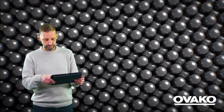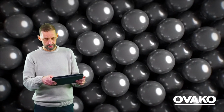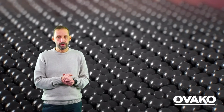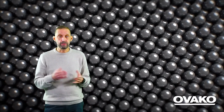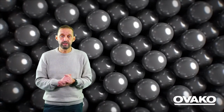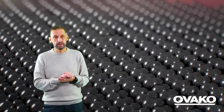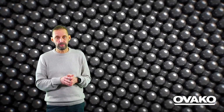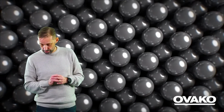Meanwhile, I can just answer a question for myself. We also talked very much before about oxygen content. We have looked at that quite a lot, and that is a strong indicator that we are using, and it still will be, but we know that it's not that alone. It's also how the oxygen is distributed and how the inclusions look like. So this is something that we keep on doing. Oxygen is still important. It's a measurement that we are following very carefully, but it will also need to be combined with how the oxides look in the product and the size distribution.